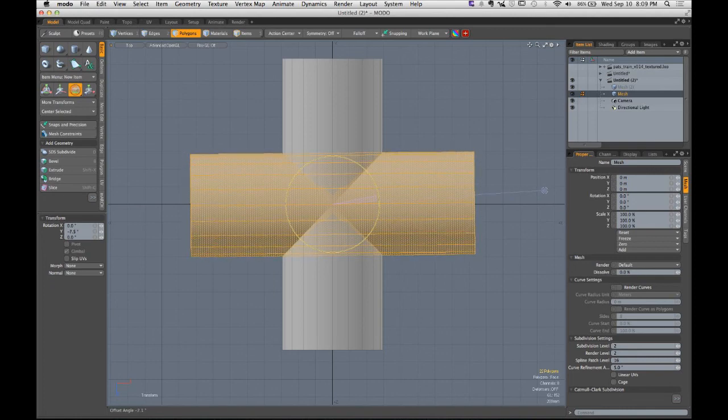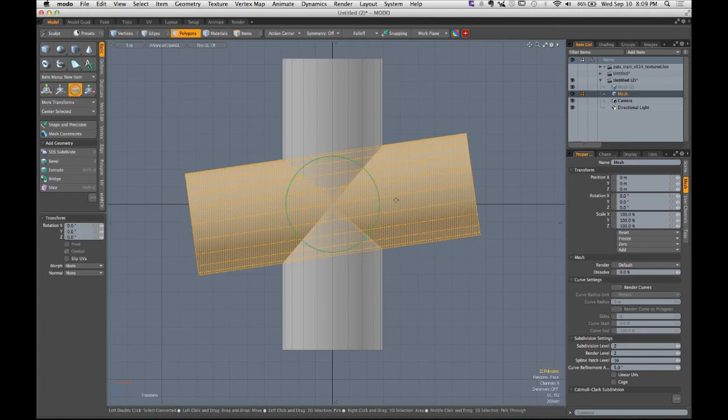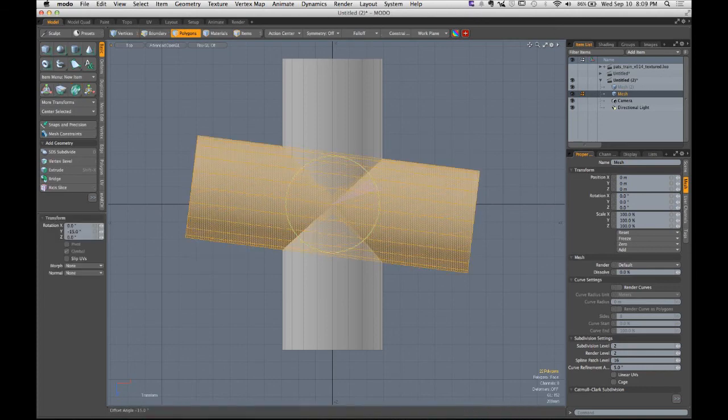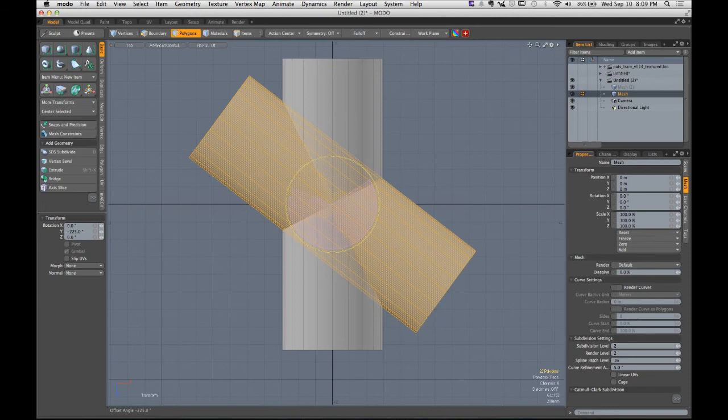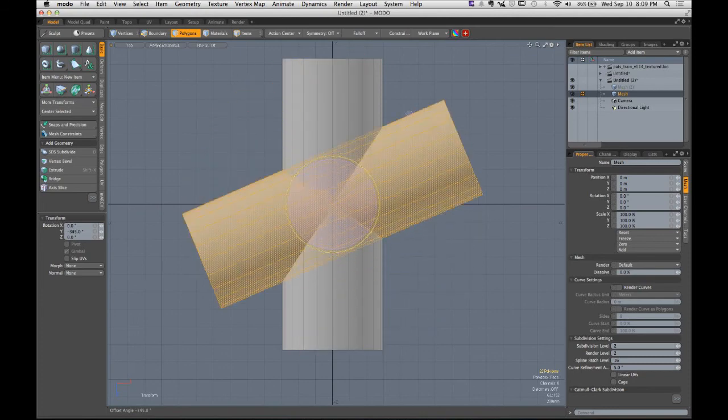How do you make it snap without actually choosing the snapping option on the top right? I thought it was holding shift, but I think I'm wrong. For the rotate command, if you hold the control key, it's going to snap to just 15-degree increments. You got it. So you recommend this rather than eyeballing it?